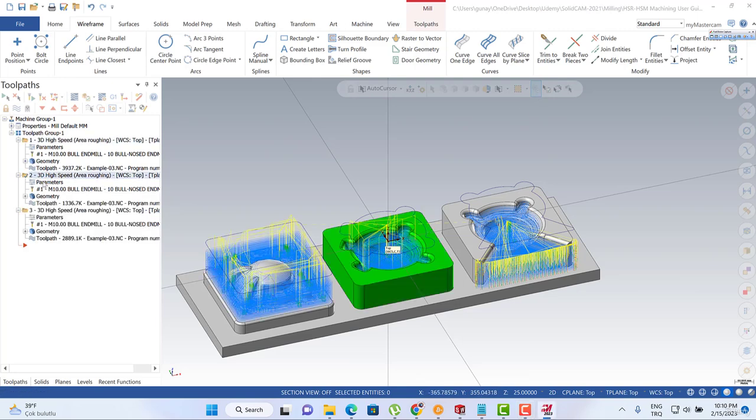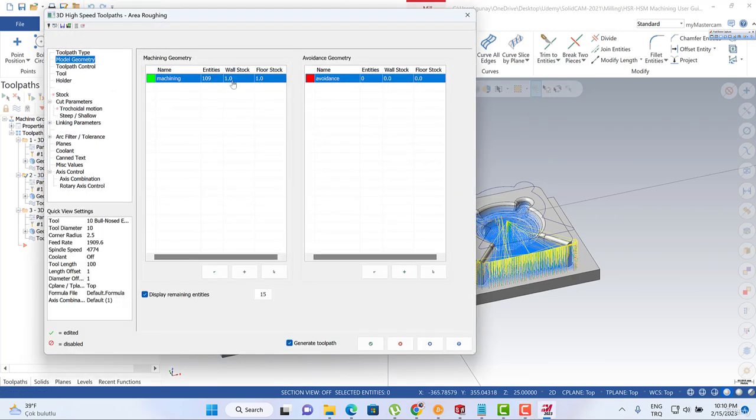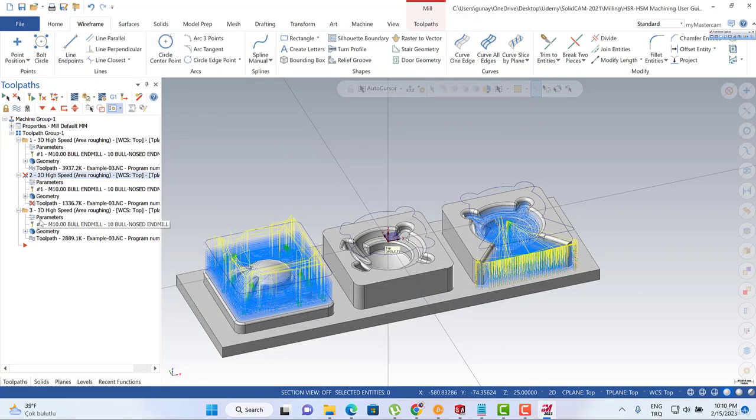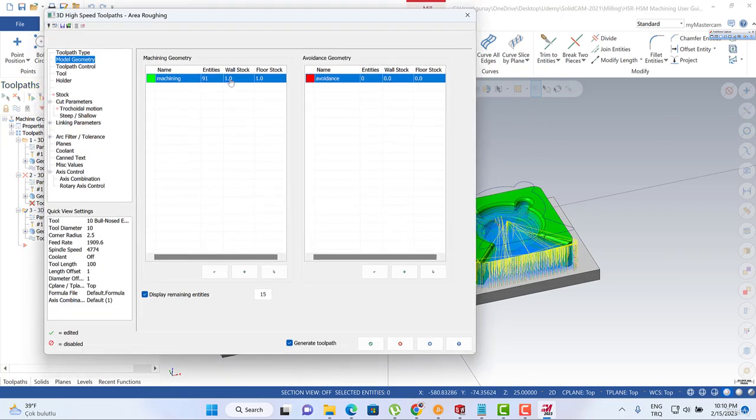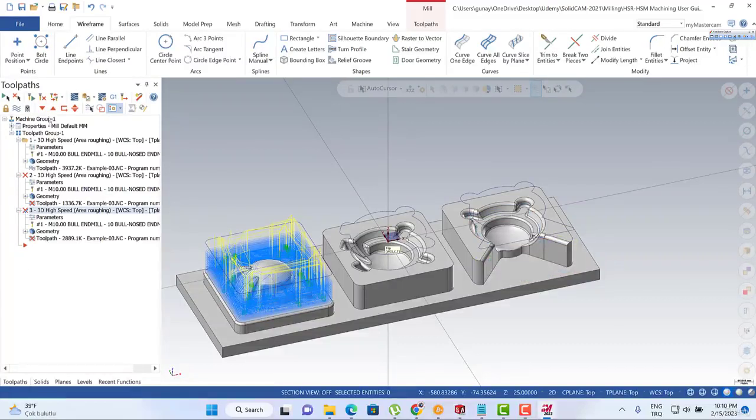And it is calculated. We can easily turn to here to make that like this. We can also unselect this part if you don't want to calculate your toolpath. You can easily turn back to here, and you can also make it 0.15, and then you can also unselect this part, and then you can hit that button to recalculate all your dirty operation.